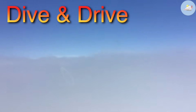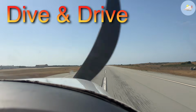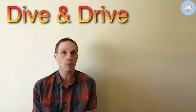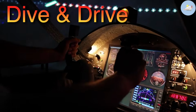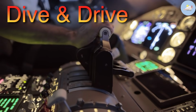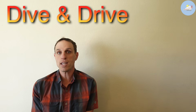is to get below a supposed cloud deck and to see the runway environment so you can ultimately land. Using the dive and drive method, you get down to the lowest altitude possible as soon as possible, and therefore you have the longest opportunity at this minimum altitude to increase your chances of seeing the runway environment. Now, the downside of this is the dive and drive method requires a lot of configuration changes, power adjustments, and you need to pay extra attention to make sure that you level off at each minimum altitude along each segment